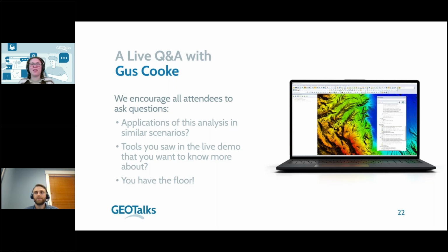And then finally, why do the shadow percent grids show meters as the unit of measure in the scale bar? And also as a second part, can we use vector data like 3D building polygons as obstructions when performing solar analysis? Two good questions there. The first: Global Mapper can treat any non-RGB raster, any raster which is just a set of cells each with a particular value, as elevation.